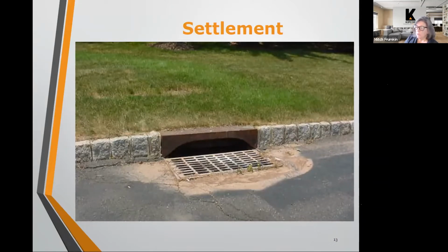and prevent clogs. Also, changing out the cast grate on catch basins is important. NJDOT specifies what's called a bicycle grate, and if you look at the old style grates, they've got these kind of deep slots in them. Apparently, people riding bicycles can really injure themselves if the wheel gets stuck in there. So the bicycle grates are intended to protect against any sort of injury from a bicyclist riding over the grate.